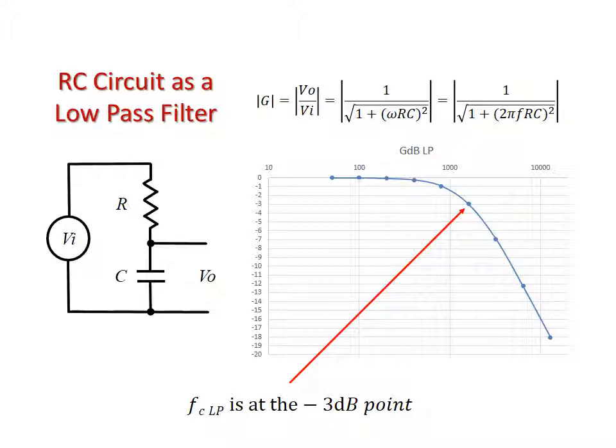If you look right around 100 hertz, you can see that there's almost no cutoff between, say, 50 and maybe 500. That's a very, very slight cutoff. But if you look at anything above 1,100, you're going to see that the signal is being attenuated very, very quickly. It's being cut off very quickly and not allowed to pass through the circuit.